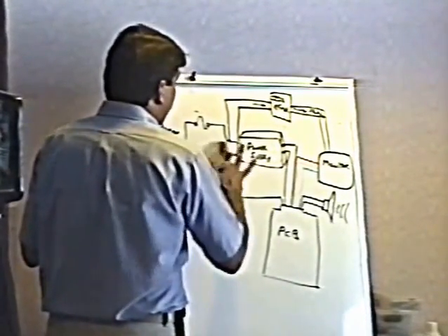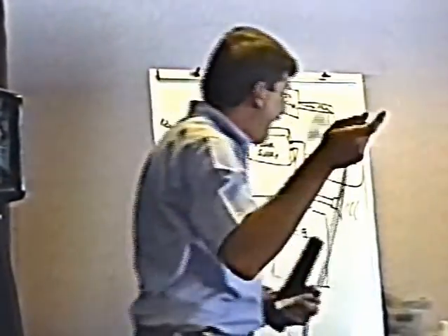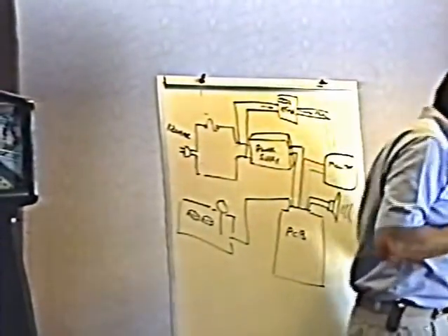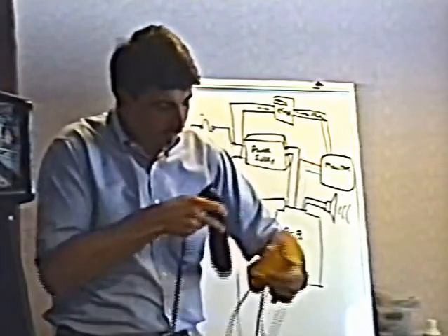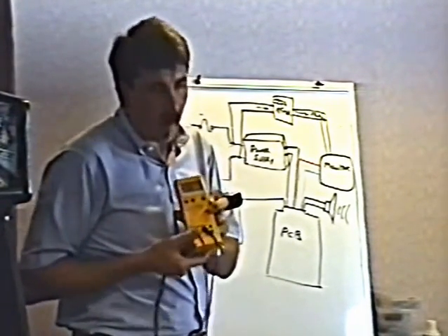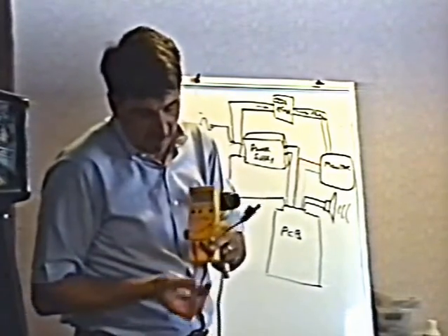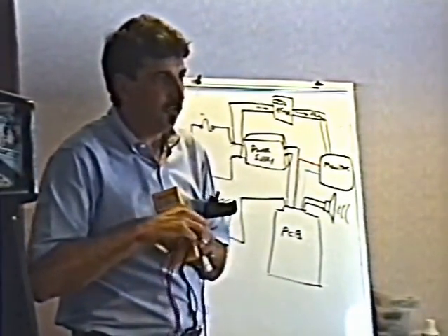There's a better way to do it, with the power turned off, with continuity. First of all, the first thing I did was this, and this is a really fast way that you can tell if the thing is hooked up or not. That is, if the cord is doing anything at all. I put my meter on the continuity beeper or on the ohm scale, whichever your meter happens to do, where it makes a beep.